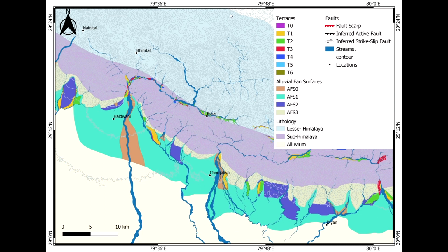Similarly, you can use these mapping tools with the help of different satellite data. You can use different digitization tools, and you can digitize the different tectono-geomorphological features, and you can prepare a detailed map for your use. We have given a demonstration of the different mapping tools in QGIS. With the help of these mapping tools, we have shown you how you can digitize the Cartosat-1 data, and we have also demonstrated how you can export the map in different formats.